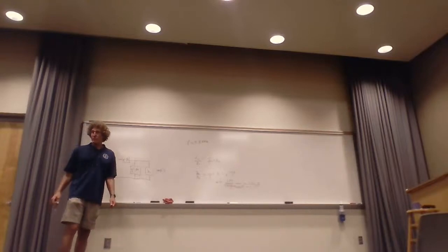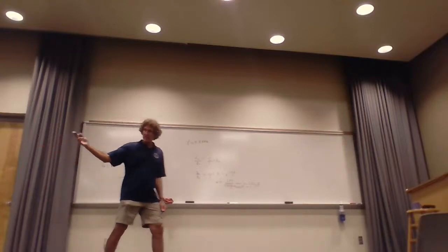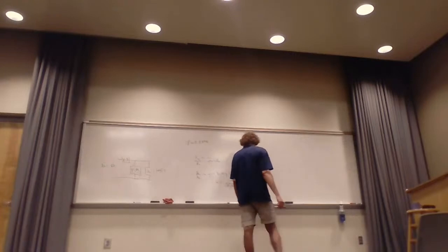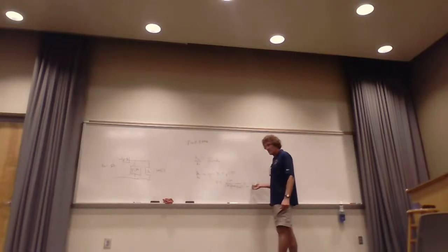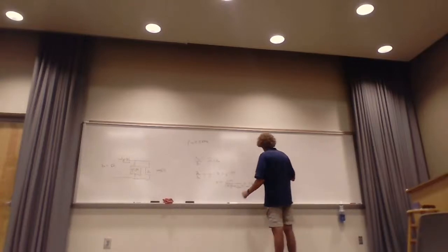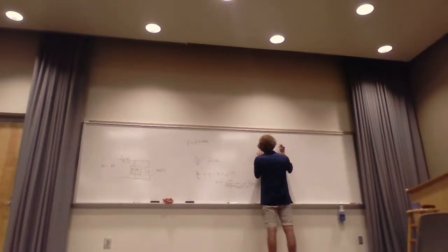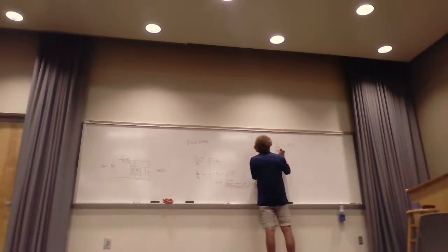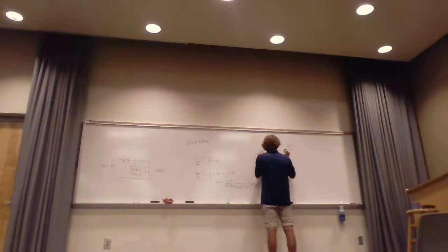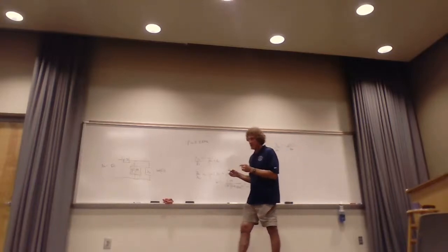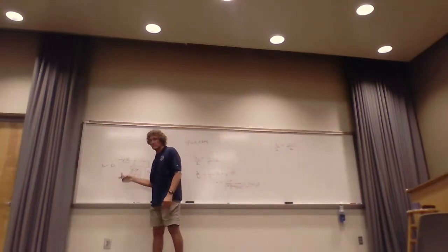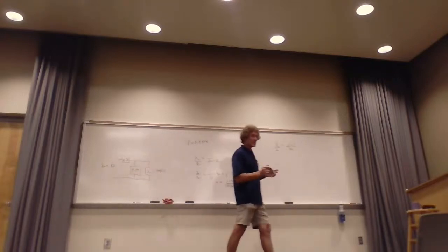So that's J 1.36. Is that what he had too, by the way? It doesn't say. He should. The capacitor? Yeah, for the capacitor, no, sorry. Is that right? Mhm. All right, now for the inductor, first I take a look at inductive reactance. That's J omega L. Then I normalize it. Now that's the normalized value, and I want it equal to this. So I just set it equal to, but you gotta normalize always.